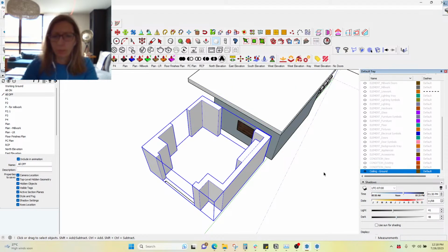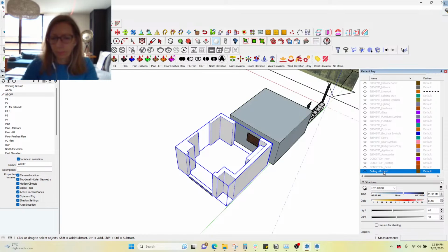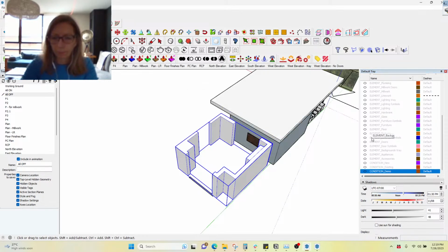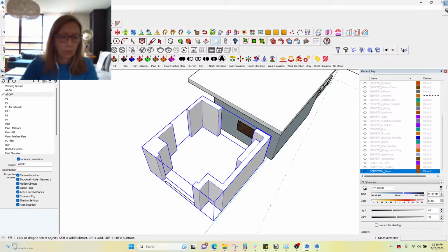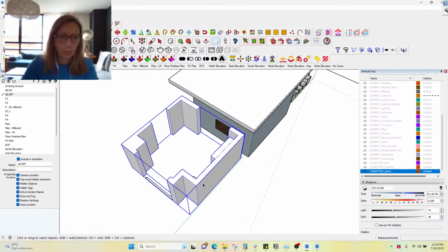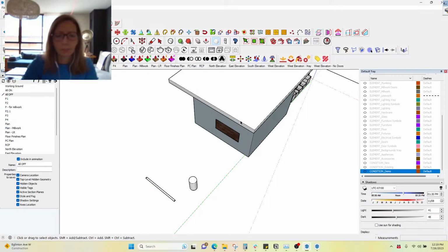And sometimes I'll just toggle them on and off to see if there's any need to keep them. So, I don't know. Yeah, I'll get rid of that one because everything should either have an element or a condition or a location symbol or label in front of them. Okay, so now I'm going to go to all off, and these are all the things that are left over. So I know that these walls should be part of element walls. So I'm going to put it on that and it'll disappear.